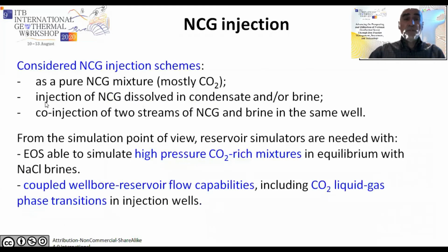So considering non-condensable gas injection schemes: the reinjection of a pure CO2 or non-condensable gas mixtures, the injection of NCG dissolved in condensate or in the brine, or the co-injection of two streams of non-condensable gas and brine in the same well.